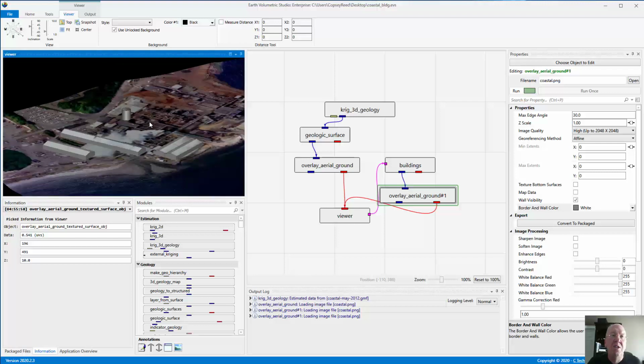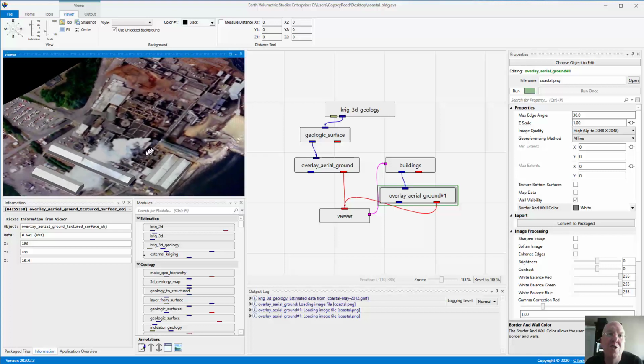And you'll be surprised. You don't need to do every building. You certainly can. But if you do the major buildings, people's eyes will fool them and they'll think everything is 3D. I've never done the cars here, but if you look at our coastal model, it has about 2 or 3 times as many buildings done, and you would not have thought that they weren't all done. Your mind just didn't go there, and you'll see. So just selectively do the major ones.